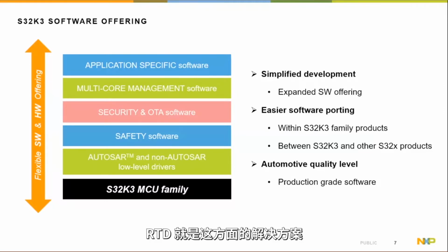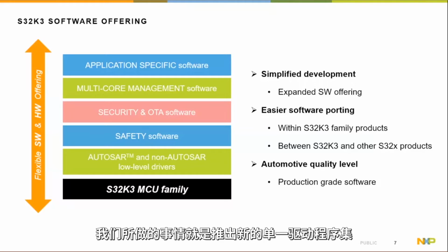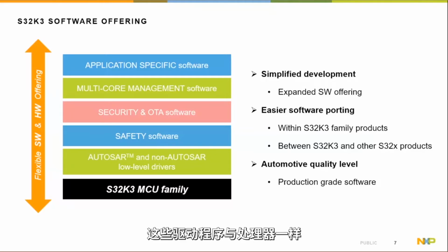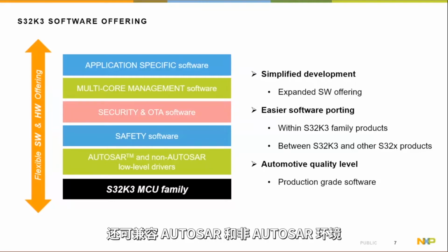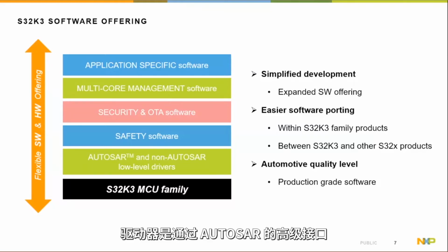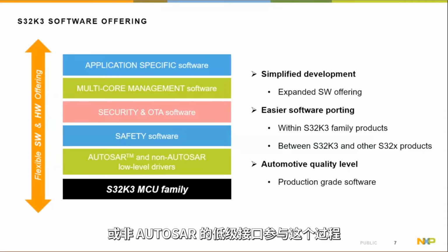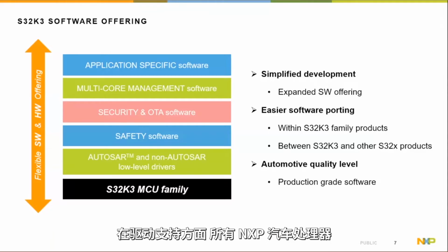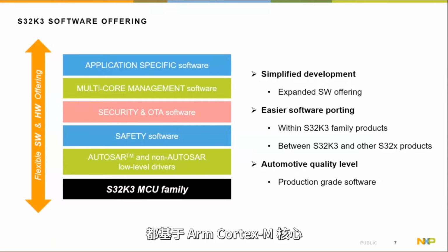So RTD is the solution for that, and what we do is we have a new single set of drivers. The drivers are ISO 26262 compliant, like the processor, so they can be used in applications up to and including ASIL level D. The same set of drivers can be used in AUTOSAR and non-AUTOSAR environments. The only difference is the way the drivers are invoked, through either a high-level interface for AUTOSAR or a low-level interface for non-AUTOSAR. The drivers support all NXP automotive processors based on ARM Cortex-M cores, which is the K3 family and K1,